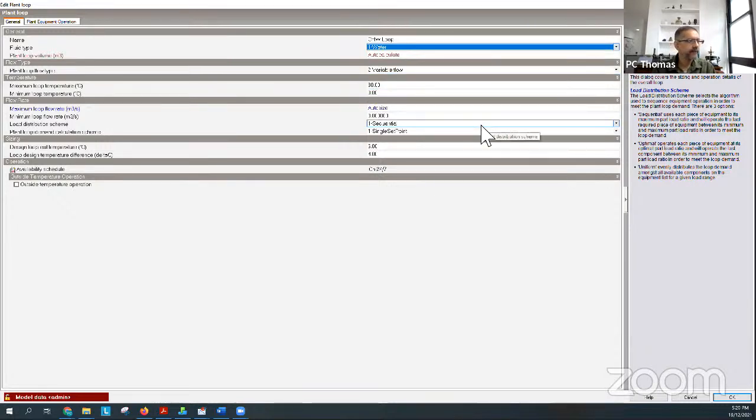And when I look down here, I see another thing that's a bit of an issue, and that is the loop exit temperature is 6 degrees. That's fine. But then the delta T for the loop is 4 degrees. Now again, typically in places like India and in Australia, we have a lot of cooling requirement, and we like a higher delta T for our design loops.